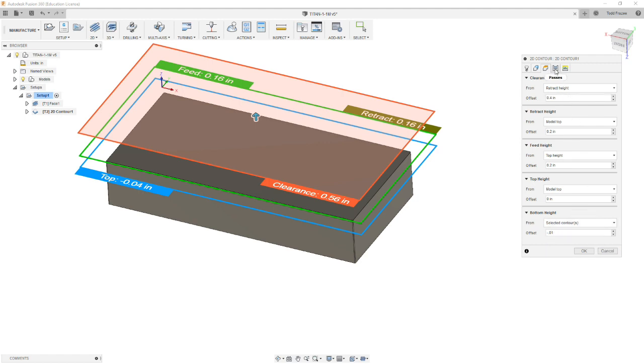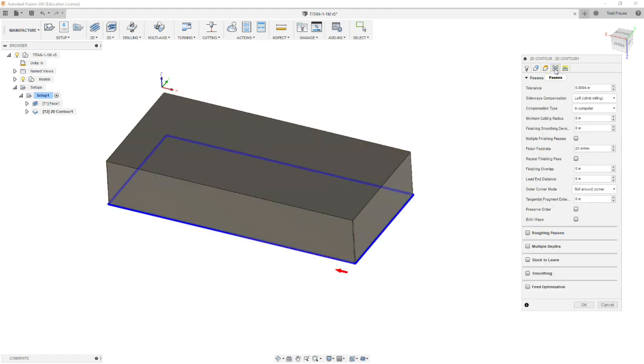Now we're going to move on to the next tab, passes. Now in Titan's original videos, he takes this off all in one pass, and in my opinion he's trying to show off what Kennametal tooling can do, but you're not going to get optimum life out of those cutters by kind of abusing them that way. We're going to take this in more than one step. It's also safer, and if you're running the right feeds and speeds, not necessarily faster the way he does it. This could most likely be more accurate as well.